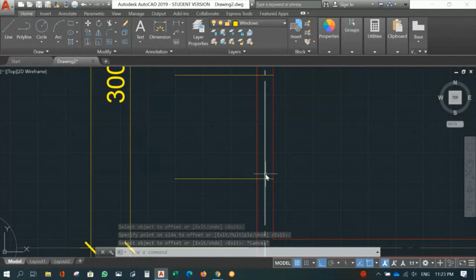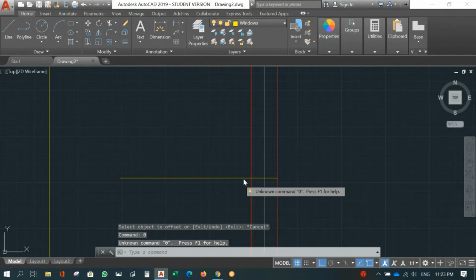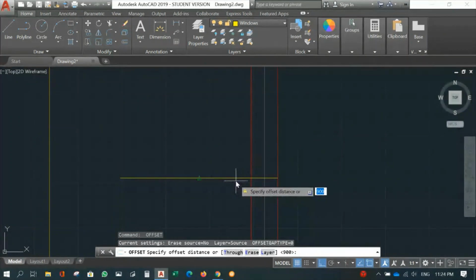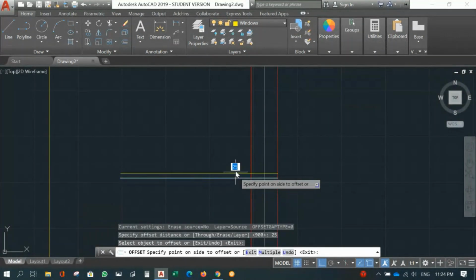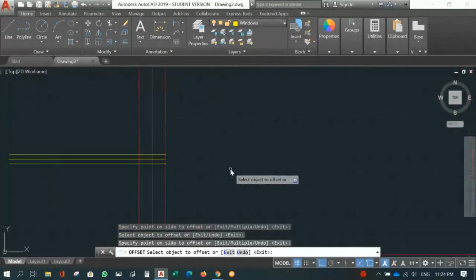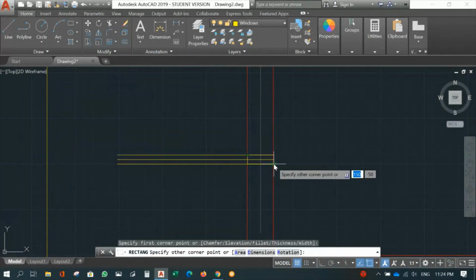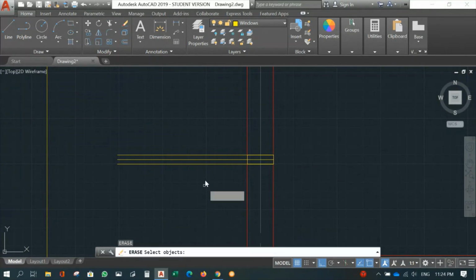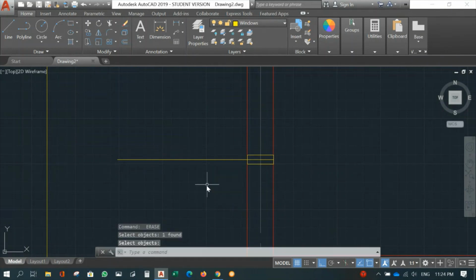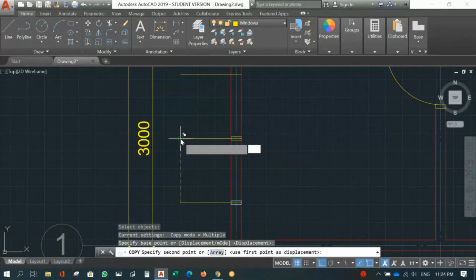And then once I have that, I'm going to create a window jamb here. So I'm going to offset. The size is 50, so I'm going to offset 25 this bar, 25 this bar, at the top and 25 to the bottom. We're supposed to have 3 window jambs here, but I'm going to create only 1. Then I'm going to pick up the rectangle as a window jamb, same as with the door just now. Click. When I've done, erase this line top and then bottom. There you are. Once I have this, I'm going to copy all this, the next line.